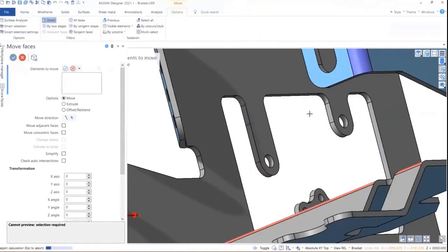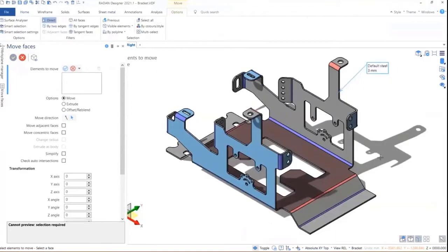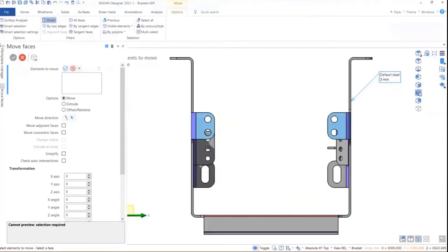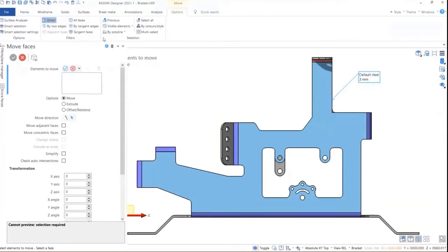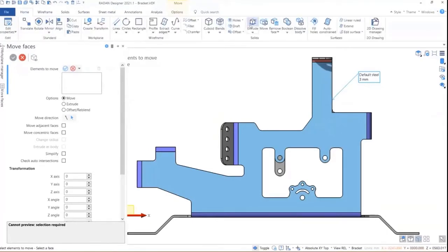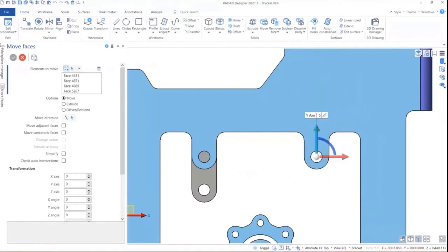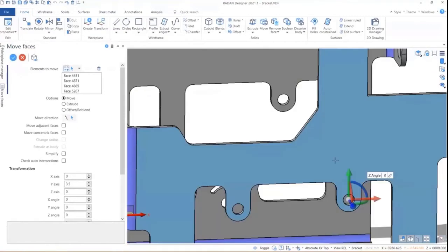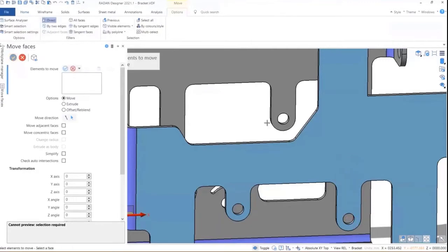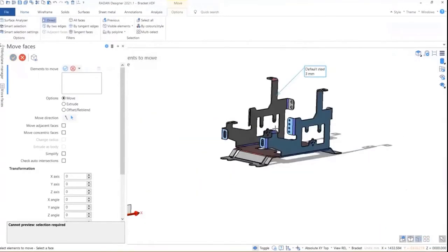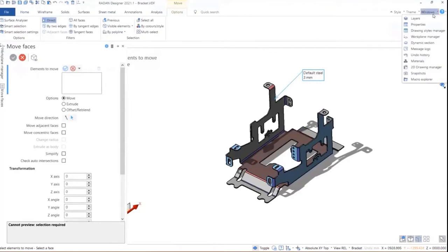So again, just reiterating, this is an imported model from another CAD system. Okay. If I wanted to maybe do a mod on multiple items, I can simply get a view on the side of my model, and I could say that what I want to do is a move. And then if I come in here and we window around those items, I'm actually moving. If I just rotate, you can see I'm moving both of those tabs because I've picked up both of those in my selection.